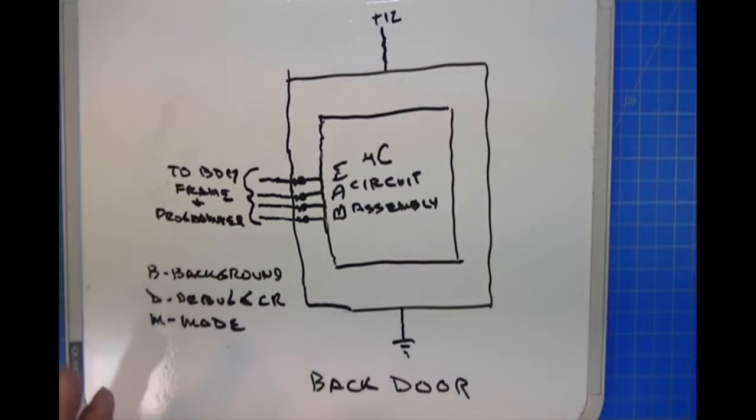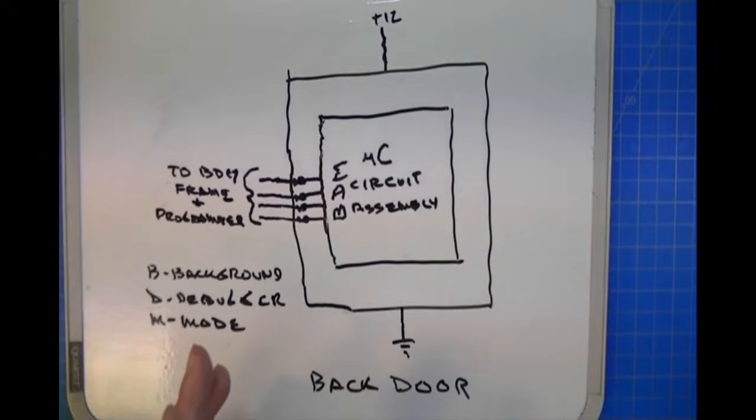But in the background, the debugger can send a command to the background debugger hardware on the silicon, which will do something like examine a memory location or write a memory location. This is happening in the quote-unquote background while the program is running. So it really facilitated debugging of microcontroller code and made it far, far better than just uploading little chunks of code and debugging that way.